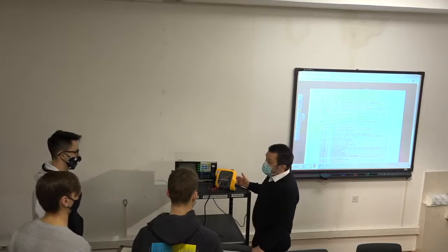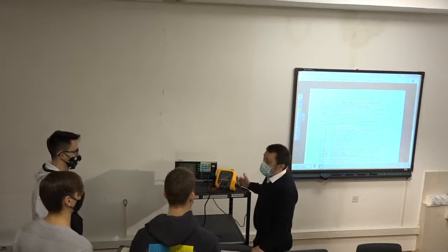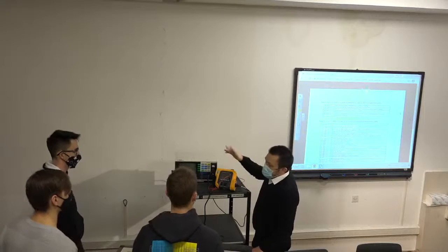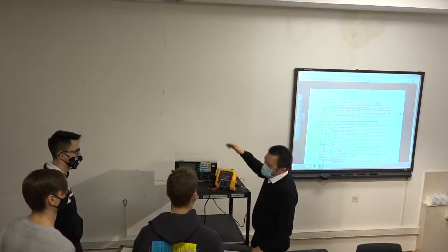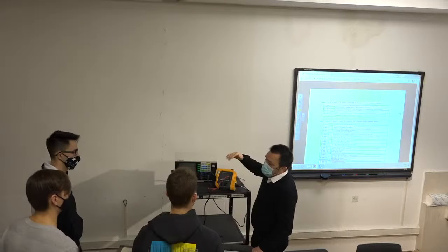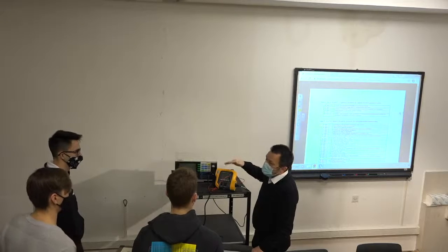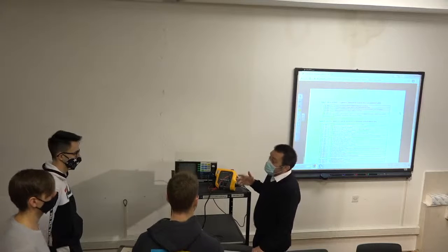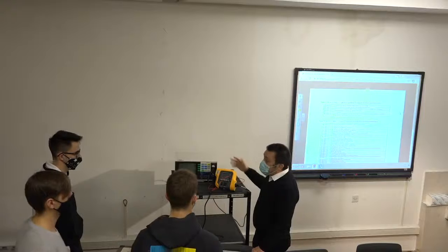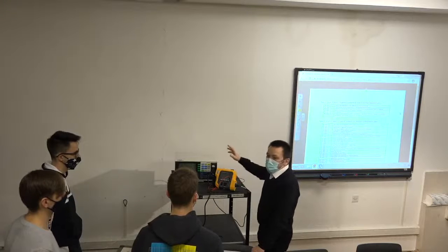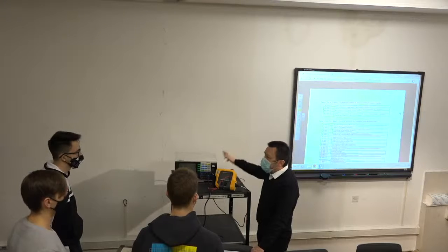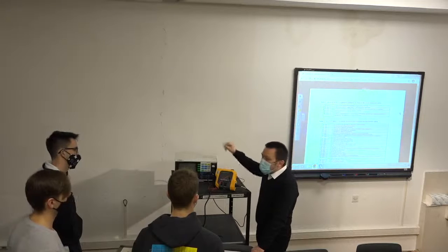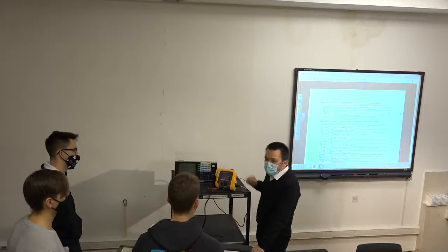The other one, if let's say the voltage drops and it's not approximately 230 volts, minus 10% it's 207 volts, so it has to be above 207 volts. If it is, let's say, less, 180, then probably some isolation of the input transformer or something like that is not correct anymore, so you have some capacitive currents flowing through that and so on.